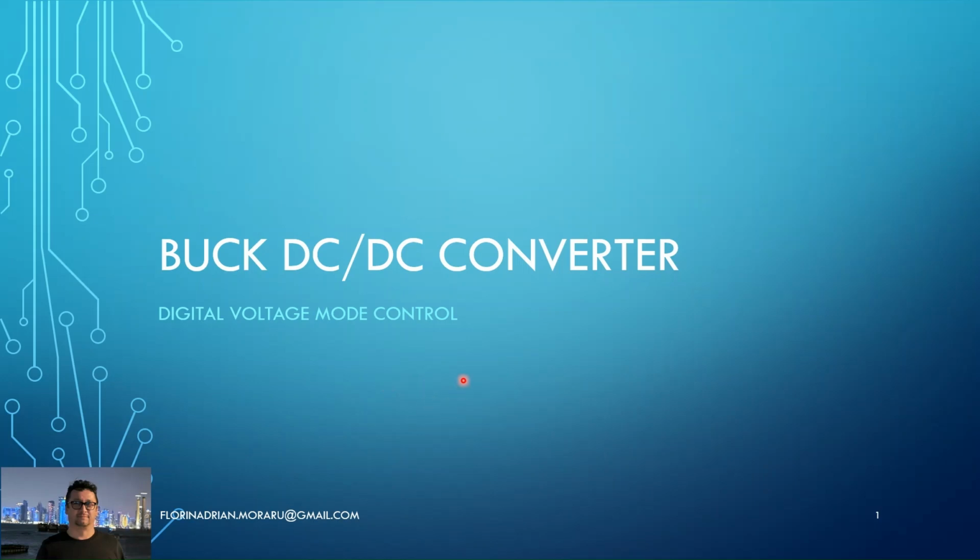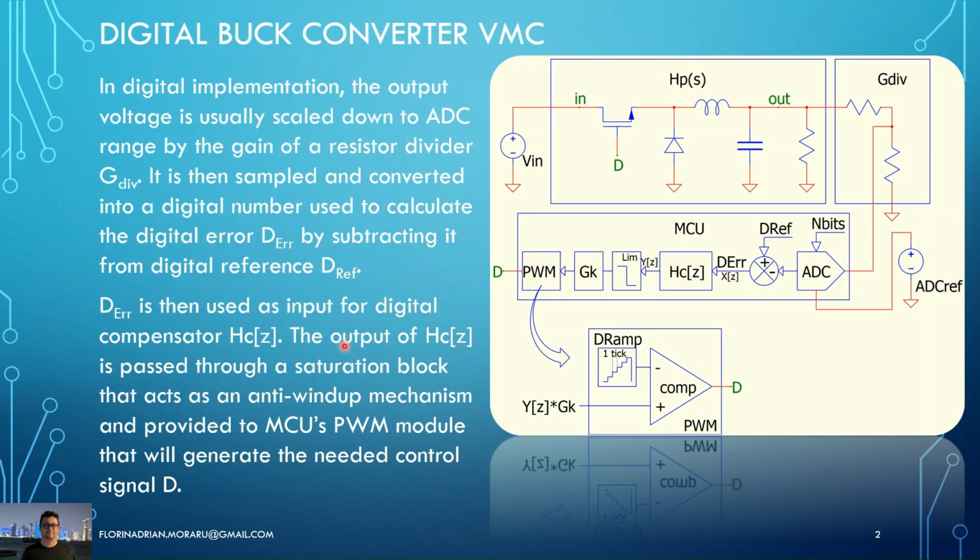Hello all, today we will discuss a buck DC-DC converter with digital voltage mode control. In digital implementation, the output voltage is sensed by a voltage divider and then applied to an ADC input pin. As soon as the sampled output voltage is converted into the digital domain, we can calculate the digital error as the difference between a digital reference and the sampled data.